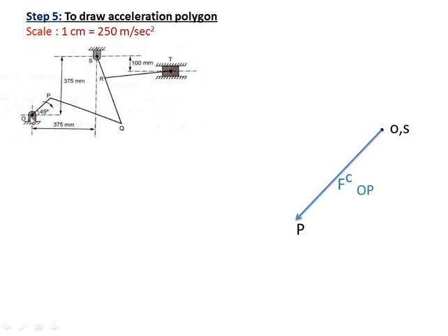We started with O, we located OP, then we are moving to PQ, so we have to follow the sequence. As we are saying link PQ, P is the center of rotation. So from P, parallel to PQ, in the upward direction. If Q were the center of rotation, then from P you would go in a downward direction. But here P is the center of rotation, so the direction should be towards P. Towards P means upward.